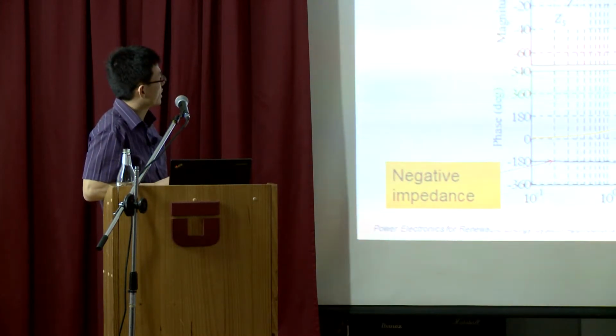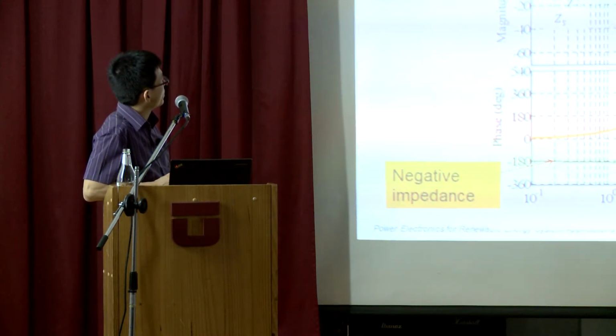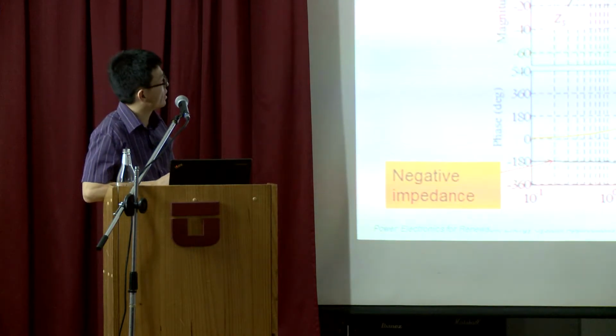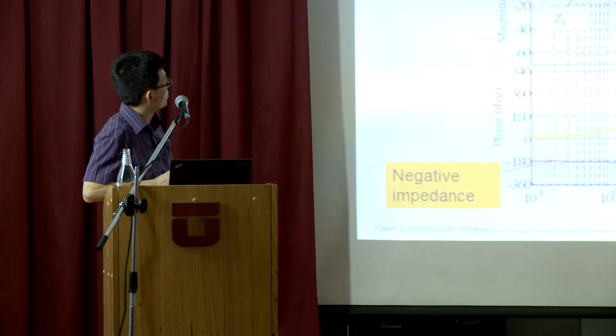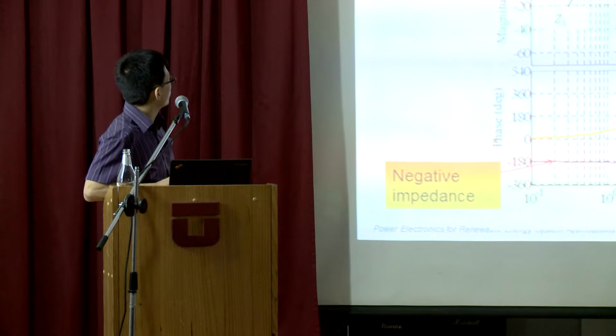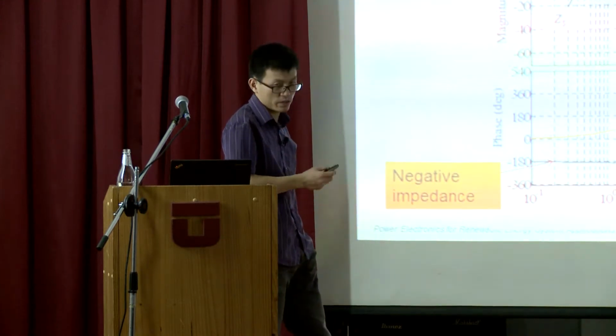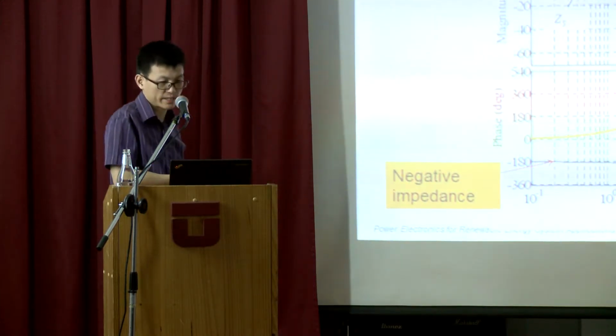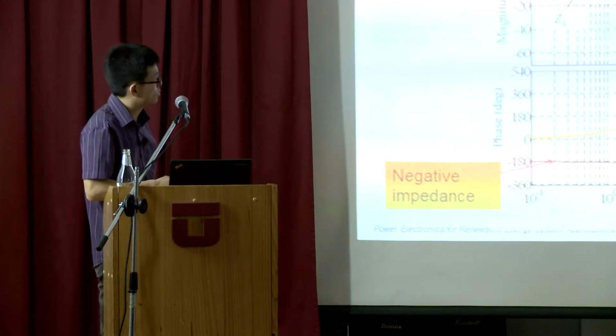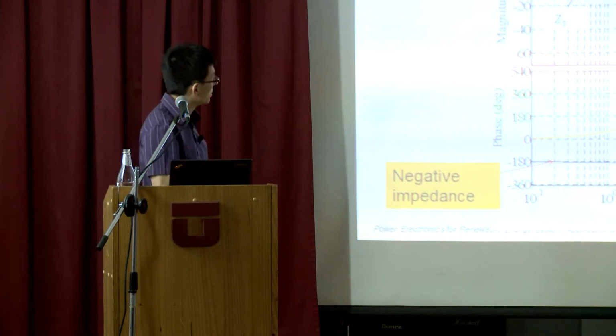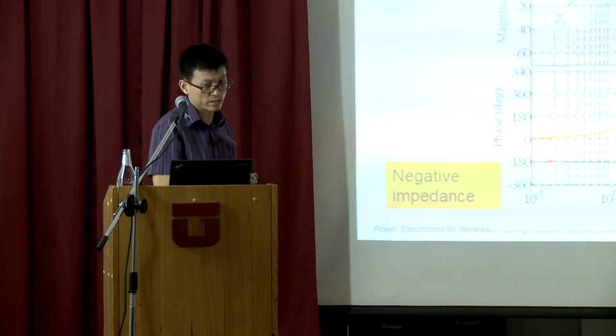What you find is when I have multiple generation systems connected in parallel using current mode control. Here I just refer to the local voltage feedback, but it is the same as global voltage feedback, because the source impedances are the same.